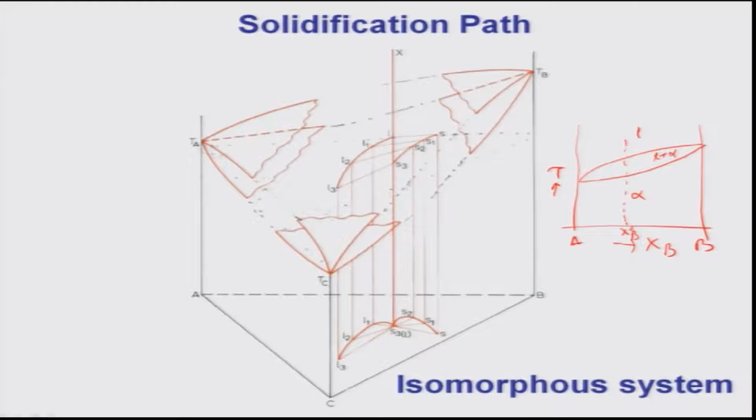Now, please concentrate here. Now, what will happen? Only the top curve is the liquidus, the bottom curve is the solidus. So, what will happen? Below the liquidus, the solid will start forming and I can draw tie lines and follow the things, and finally the whole liquid will solidify at this temperature. This is TL, this is TS, right.